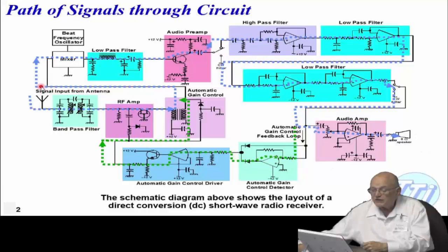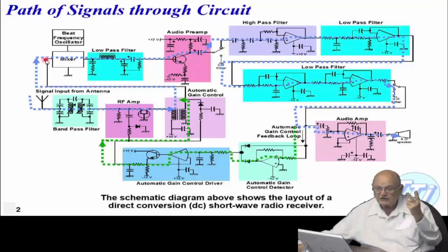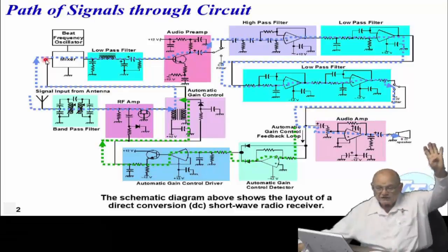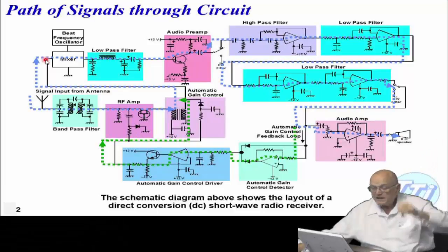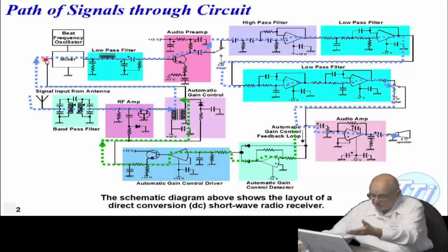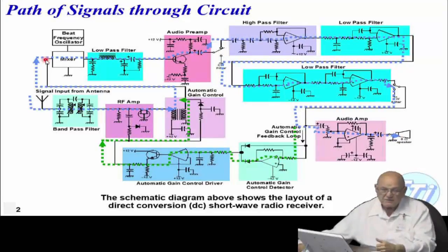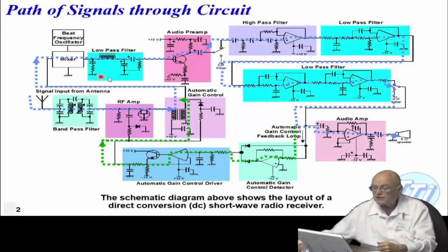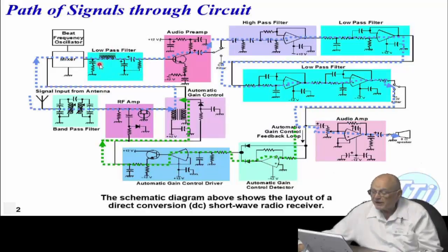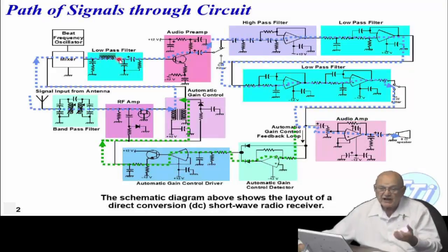Right here, the RF signal comes up to what we call a mixer. A mixer is a circuit that will take 2 signals and mix them together to produce the sum and the difference. So there are 4 signals there, okay? And the system selects the lowest frequency because it's easier to work with low frequencies. It picks that through the use of this low-pass filter. See that? It's called a low-pass filter. Now you'll learn how the capacitor works and how the inductor works later on today, specifically to be able to select the low frequencies and reject the higher frequencies.